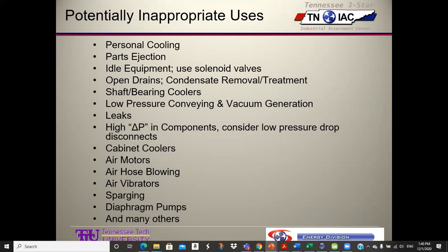The idea is there, if we have lines, sometimes you'll have maybe a big manufacturing line that's supplied by maybe a 2 or 1.5, 2, 2.5, 3-inch compressed air line. When that whole system goes down, it may have a general power switch, and you can put a solenoid valve that will shut off the air to that line because you're not manufacturing anything.